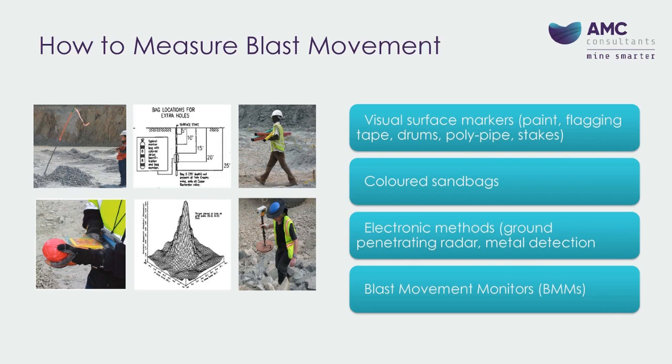Another disadvantage was, whilst they were able to measure subsurface movement, this subsurface movement was not able to be defined until the sandbags were actually uncovered during excavation. And by this point, it's often too late. The advantage, however, was they were able to measure subsurface movement with the sandbags that were recovered.